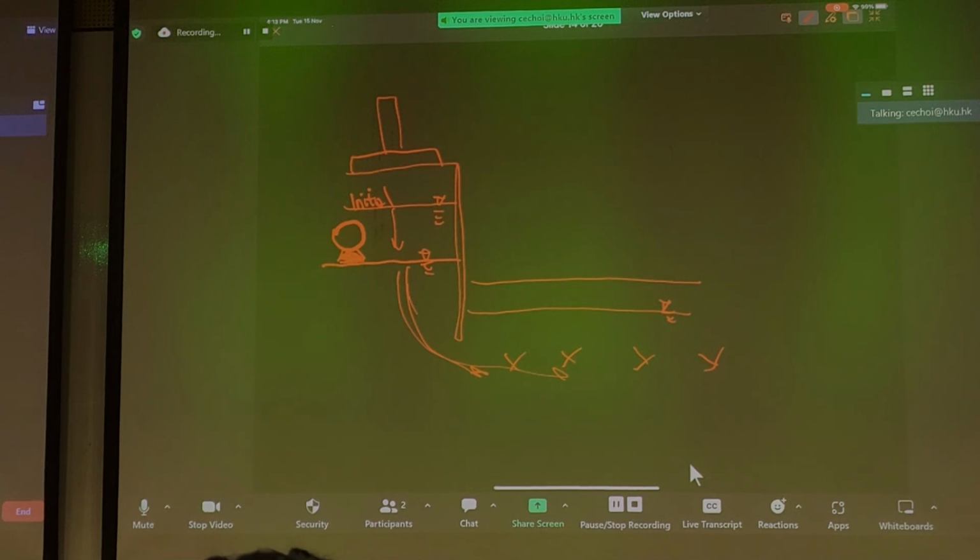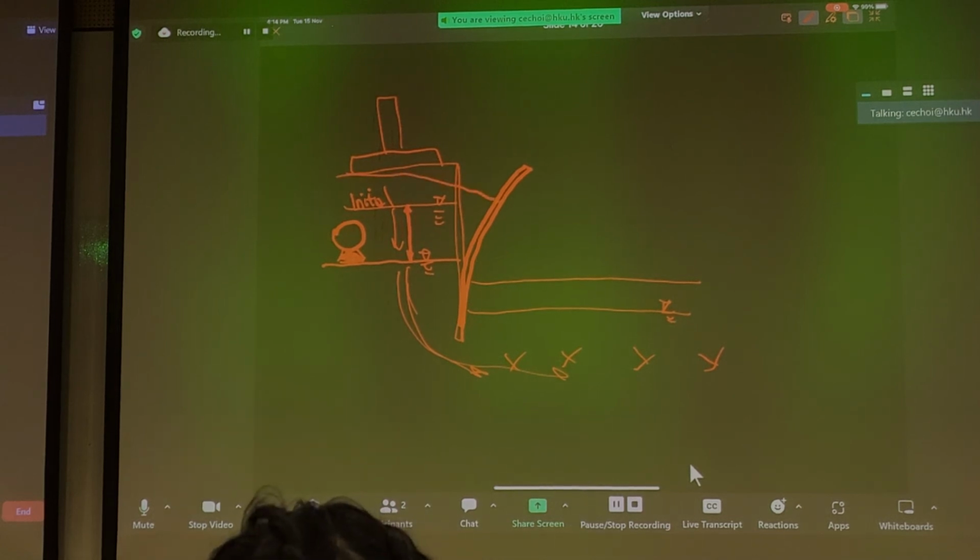If you can calculate how much you need to draw down outside relative to inside the excavation, then you can calculate the consolidation in terms of settlement. More often than not, Plaxis may only give you settlement due to deformation. When we calculate the excavation sequence, we expect something like this, right? Settlement here. But this is only due to soil-structure interaction. If you also have a drawdown sequence of your groundwater level, you also need to calculate what's the effect of drawing down the water outside by 1 meter, 2 meter, 3 meter, and you need to add these settlements together.